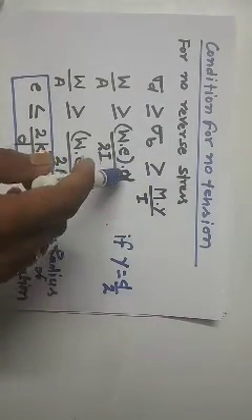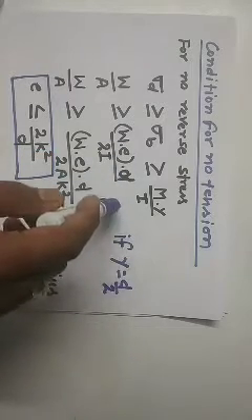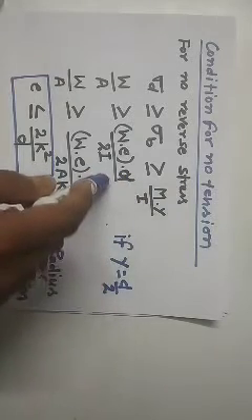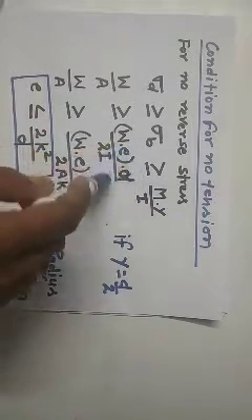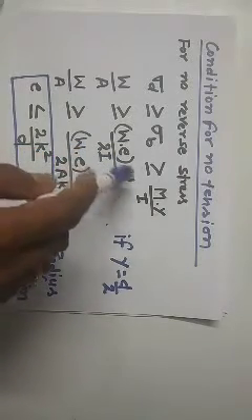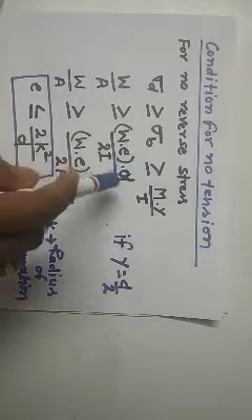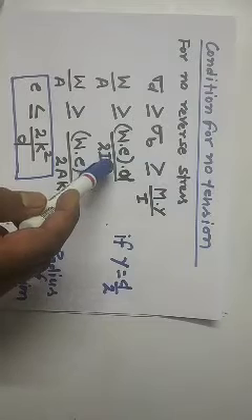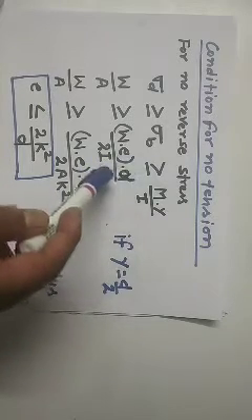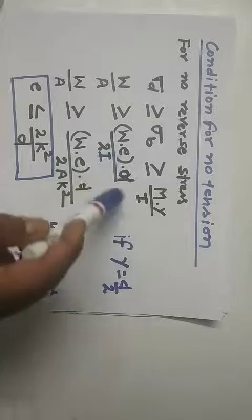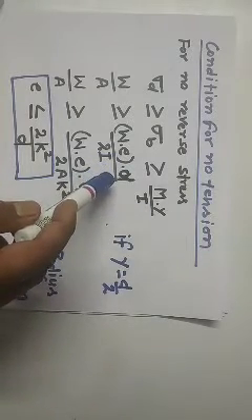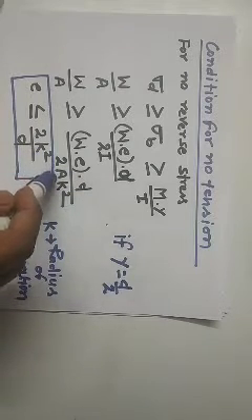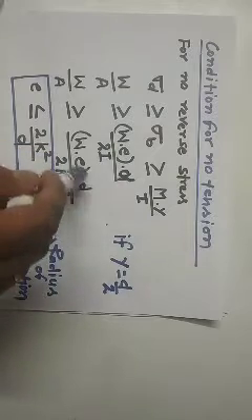Now where load is applied on the x-axis, we will take the moment about the y-axis. Be very sure: if load is applied on the x-axis, then the moment will be taken about the y-axis, and if load is on the y-axis, then the moment will be about the x-axis. In the problem we will put the value of I directly in the equation. Here I have kept it general because we are going to generate a formula of eccentricity which limits it to a certain zone.